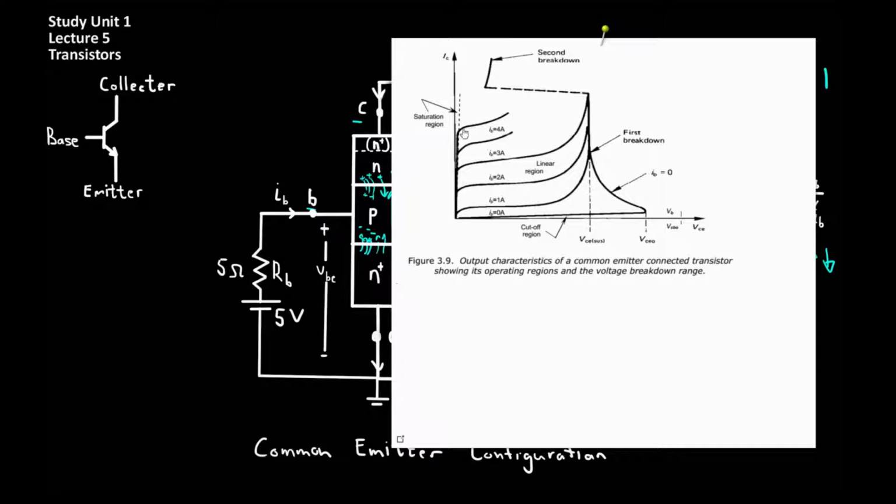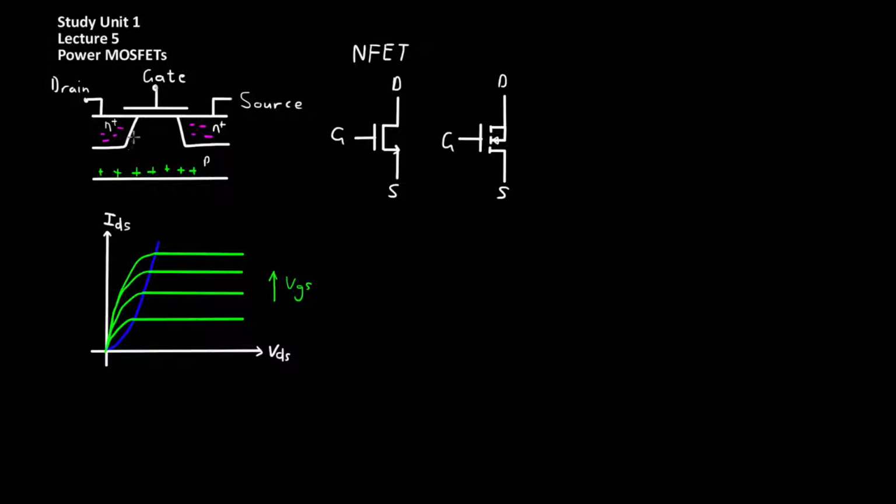through the device. Shown here is the basic structure of a MOSFET transistor. The MOSFET transistor consists of a drain, a source, and a gate. Application of voltage to the gate allows for the control of a conduction channel which forms between two n-doped regions through which current can flow.